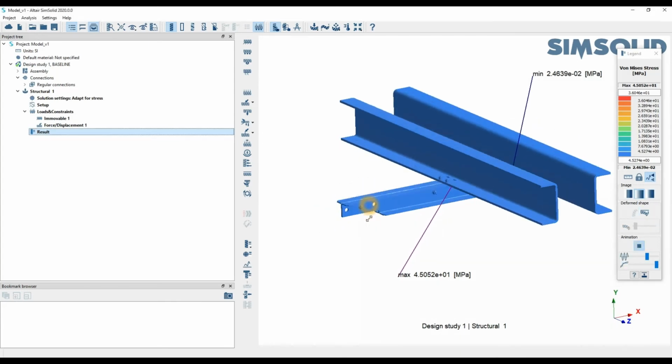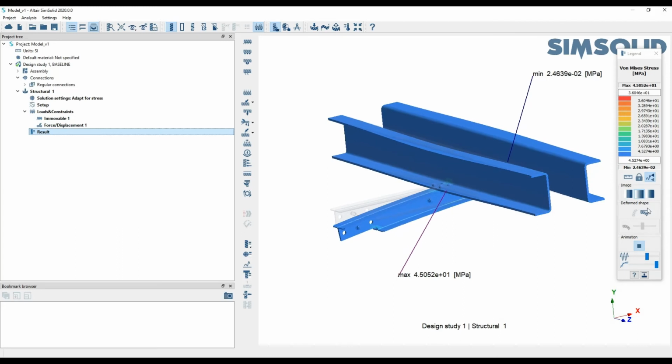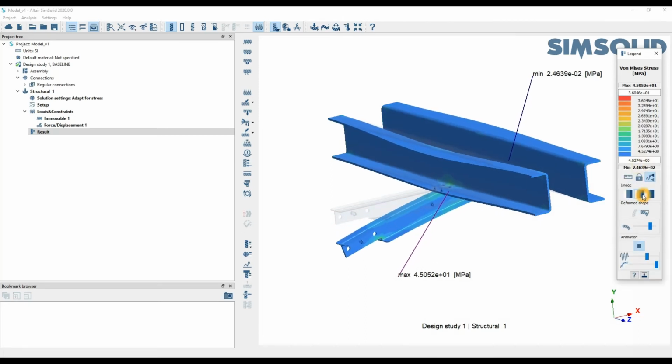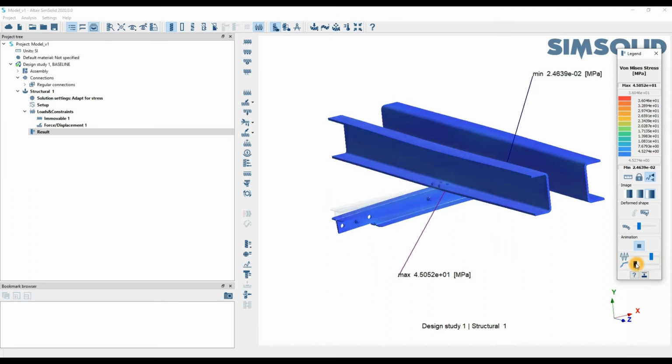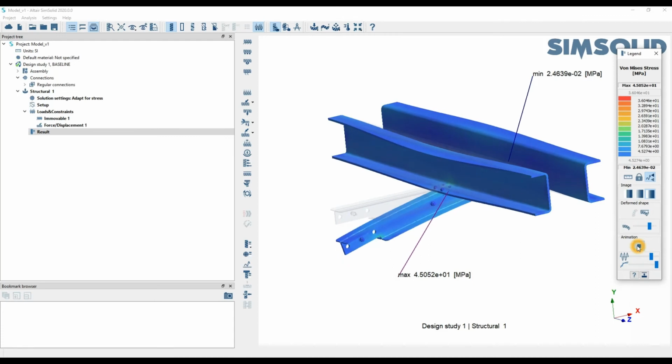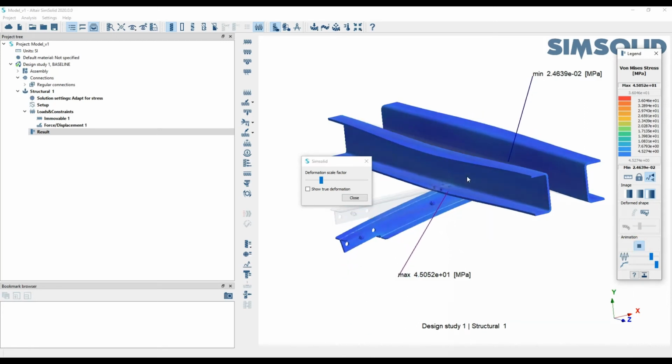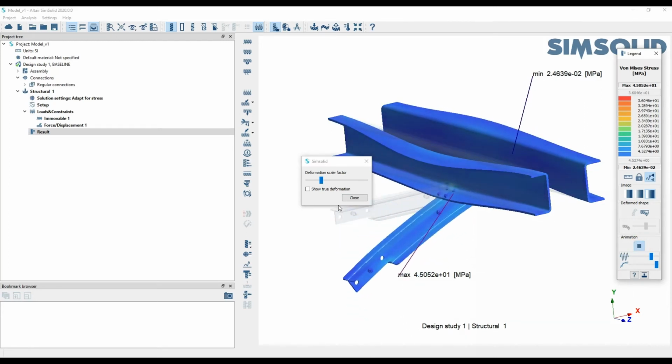You have your usual play button to look at the way in which your simulation is played. You have 3 different image options as well, so you can look at your contour in discrete fashion, in a slightly interpolated way as well with 12 colours, or you can look at it fully interpolated as well. You can change your oscillation speeds and how discrete or continuous your animation is. This button here also helps specify your scale factor deformation. So if I was to click play, you can see it's a lot more exaggerated and it's done for graphical purposes only.